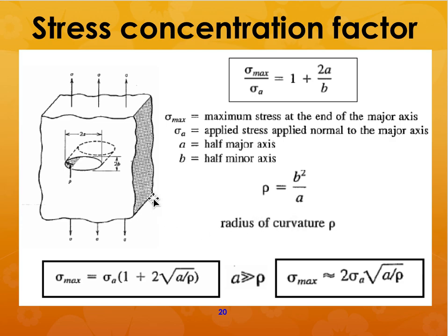So if you know the major and minor axis of your hole, you can calculate the radius of curvature. From that, you can calculate the maximum stress that is being applied on this sample, or the stress at this edge here.